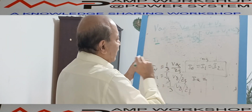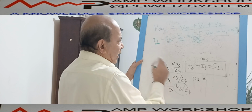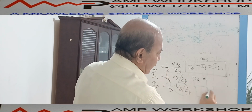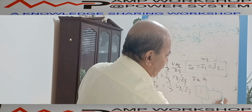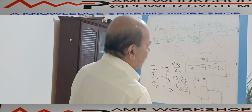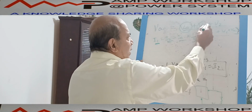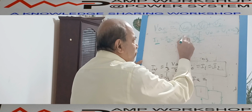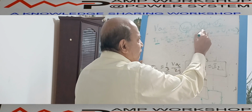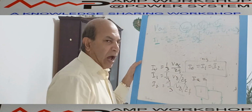That means positive sequence current, negative sequence current, and zero sequence current are equal, and the voltage VAG, that means in the network we draw here, the VAG voltage with respect to ground, this is neutral. This is connected through the impedance. If we consider these two terminals, that voltage is V0, V1, V2. These 3 voltages are connected in series. If we connect V0, V1, and V2 in series, then we are getting VAG. And again, the current flowing through V0, V1, and V2 are all equal.